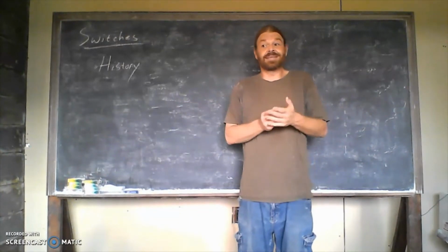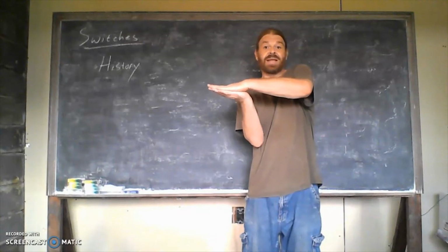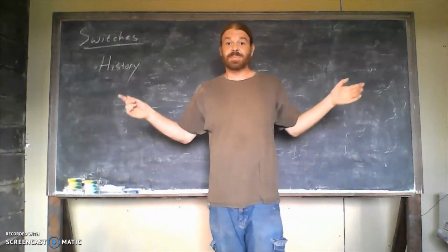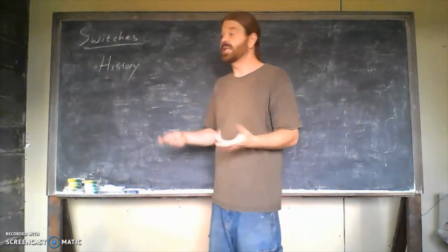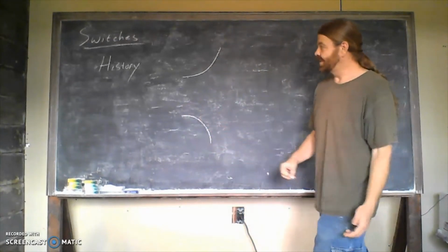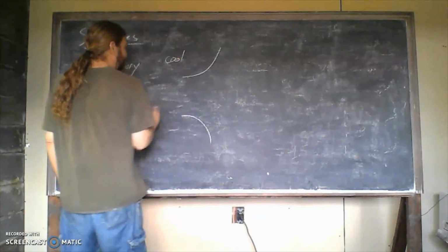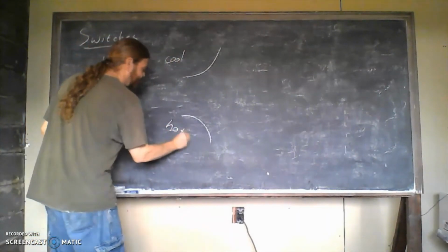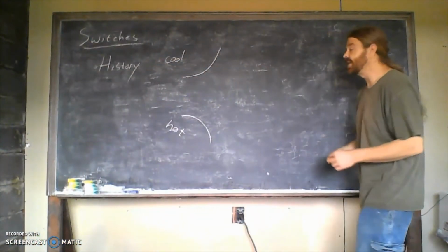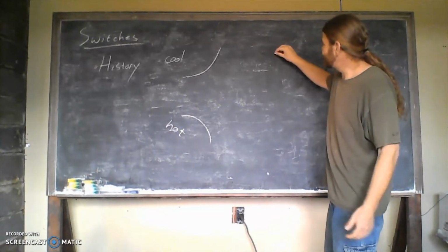And it's not equal for each type of metal. So if we have, say, nickel and copper together, when we heat it up and cool it down, those 2 metals are going to expand and contract differently, which causes it to curve. Curve up when it's cool, and curve down when it's hot. Depending on the temperature, there are some more precise values that go in there. You may have seen that old thermostats used them.